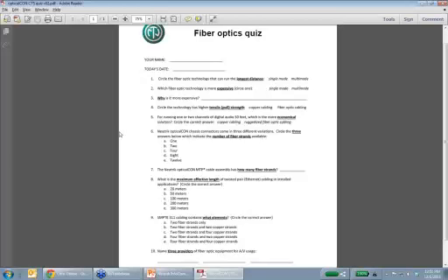If the user has RF interference issues, worries about lightning strikes or EMI, whatever, fiber is a good solution. If the customer has distance limitations which cannot be overcome with copper or which require a whole bunch of copper repeaters which wind up being expensive and cumbersome, well, then fiber is a better solution. If the customer has a whole lot of patch points, patch cables, points of failure which can be reduced by multiplexing and going to fiber and simplifying the solution, well, then those are other good sells as well.